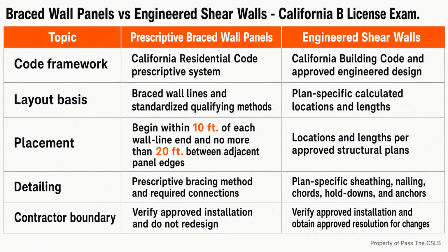Panel edges deserve close attention because a shear wall is not just a field of plywood or oriented strand board. Its capacity depends on the sheathing transferring load through specified fasteners into framing. In California seismic force-resisting systems, unblocked shear walls are prohibited.